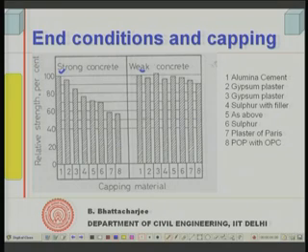If we consider this as the strength for strong concrete, 100, whatever alumina cement gives, you have done capping with alumina cement. That means, we had cylindrical specimen like this, and we have done a capping here and here. After capping the loads were applied from both these directions. So, when you put alumina cement, the strength that we get, we call it 100%.